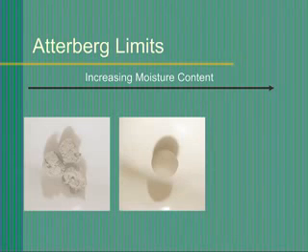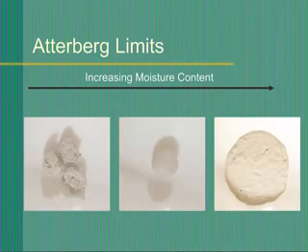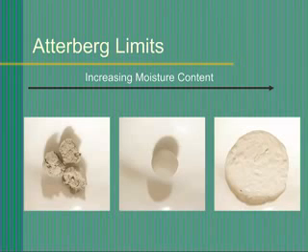If additional water is added, further increasing the moisture content, the soil will eventually act as a viscous liquid that will ooze and flow. The Atterberg limits are water content measurements that define the boundaries between the three soil states of semi-solid, plastic, and liquid.